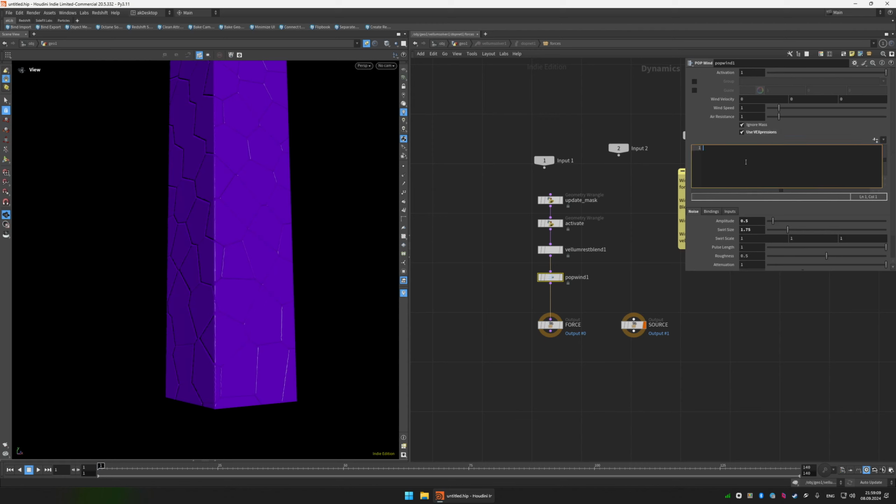So I use an expression here. I just use @P.y, and I multiply this by a simple expression again. I want to fit the frame, and I want to fit this from 115 to 140. And I just want to multiply this from 0. So basically on frame 115 it will equal 0 multiplied, on frame 140 it will equal 1, and then the basic velocity is -3.